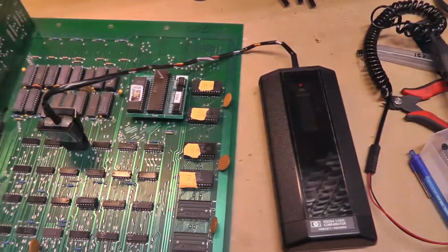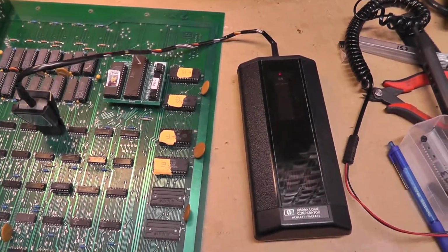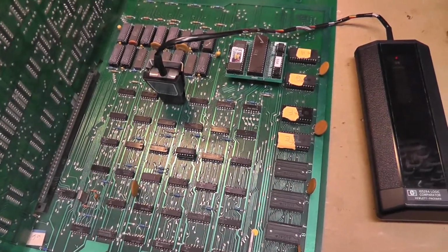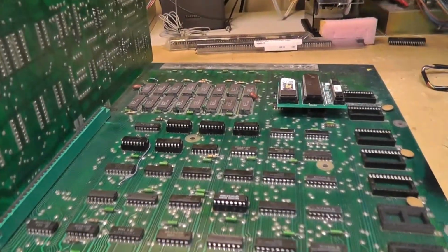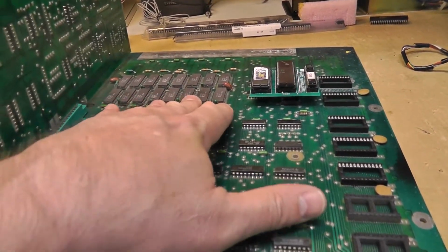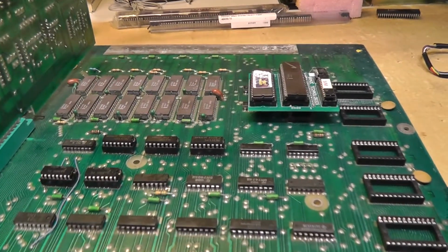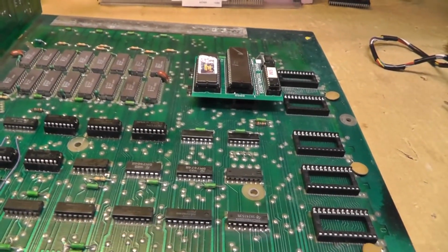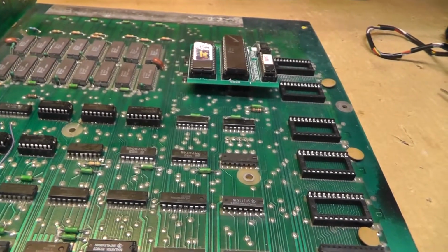I guess that's my best guess right now. It does look like my comparator reads this board fine on the outputs there, so I'm going to do it. Alright, I have 3 new 74157s in there. I have my doubts on whether that's the problem or not, but let's see what we get.